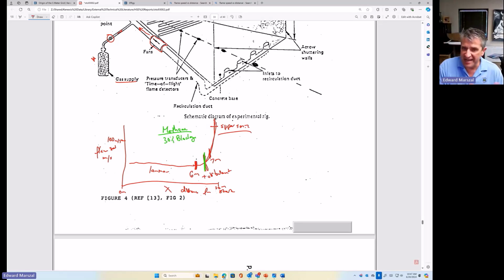So you'll see that once you get there, that flame speed is laminar, and then boom, it's going to go up. And that point where it transitions into supersonic, that's what we want to avoid, because that's what's going to cause our vapor cloud explosion. This is where that conclusion came from that said, well, 6 meters is what we're worried about, so let's put our materials on a 5-meter grid and do 20%, 60%, which even gives you a little bit more cushion. Now, this is flame speed.